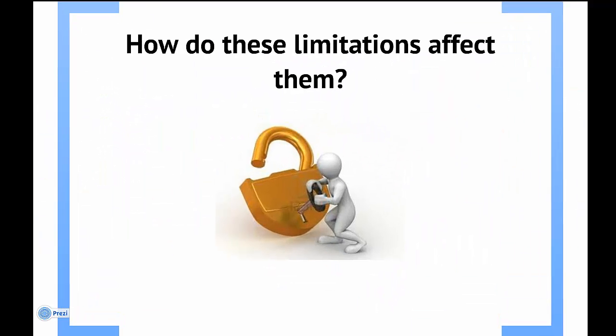How do these limitations affect them? Well, as just seen, the slow movement of the dragline requires them to remain in the one pit. So the idea is to minimize any walking or positioning time during the operation. The dig and dump radius, the dig depth and the dump height all contribute to both the width and depth of the strip being mined, as well as the methodology used to dig the material.